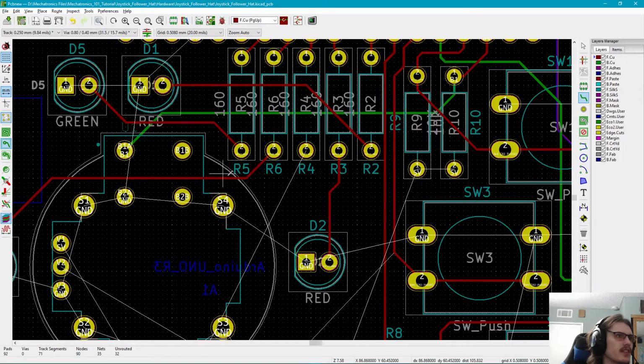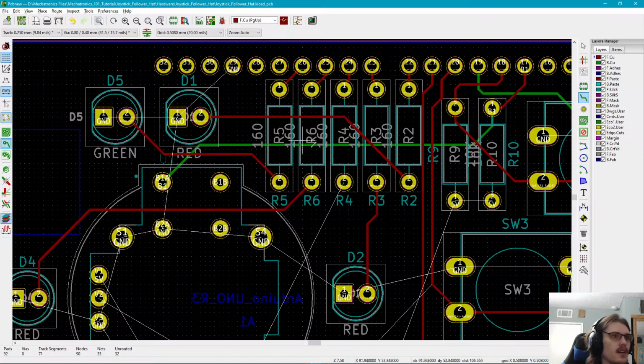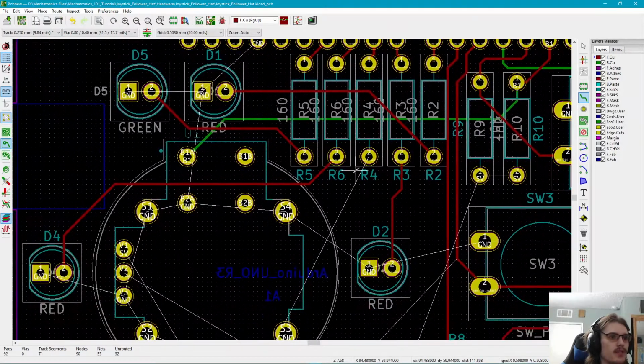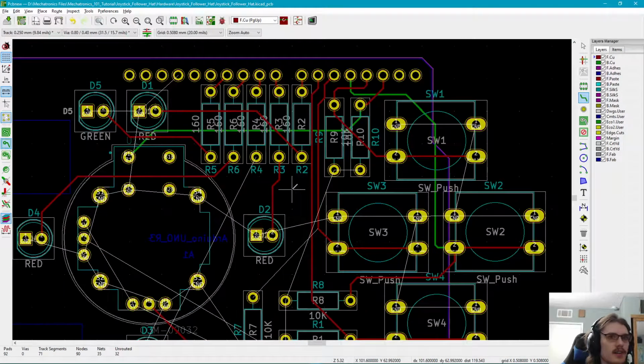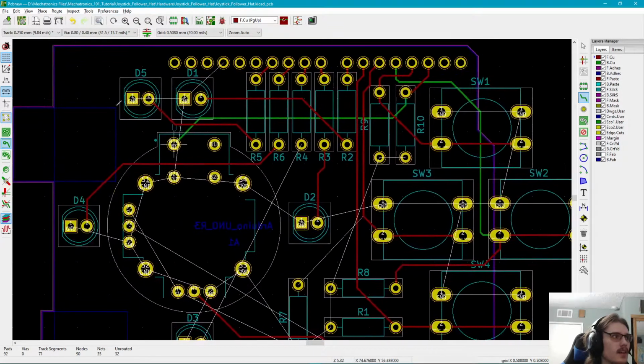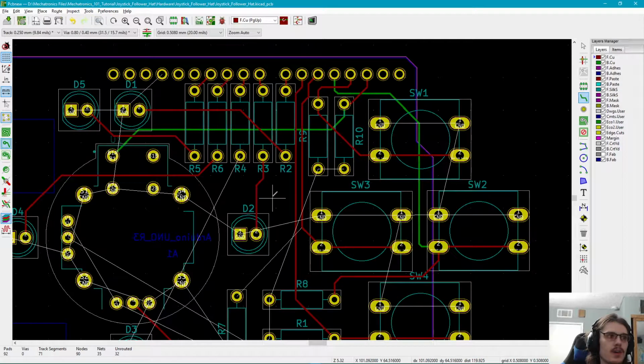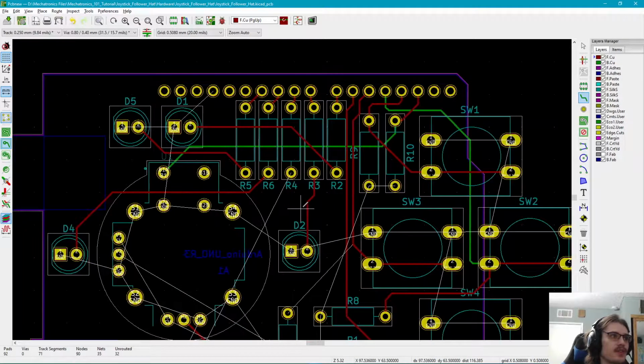If you're curious to figure out what width is best for your signal on your PCB, they have PCB calculators where you enter the desired current and how long your trace is, and then it'll give you the width that you should be using, just through some basic algebra equations.